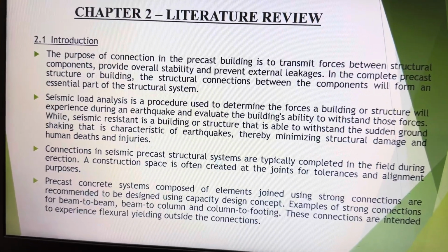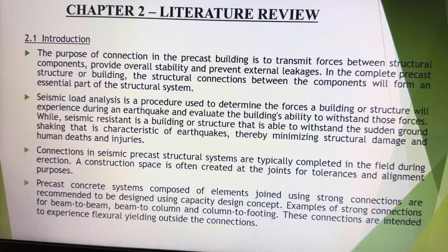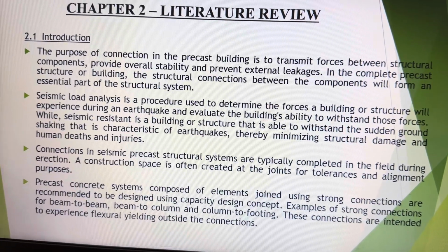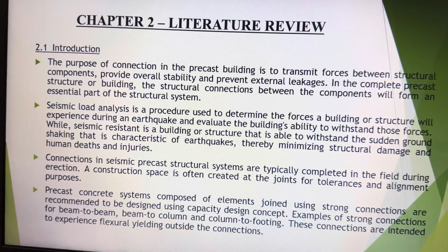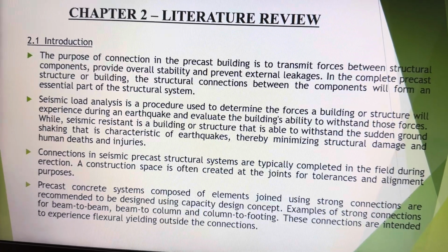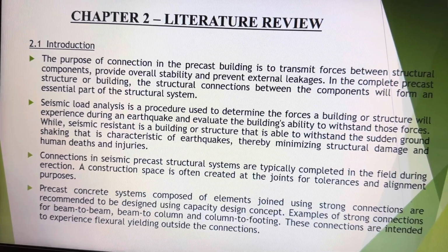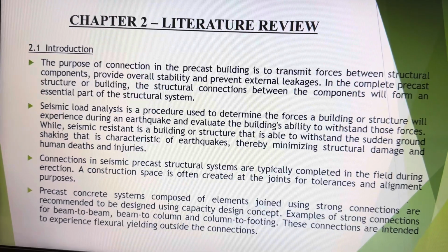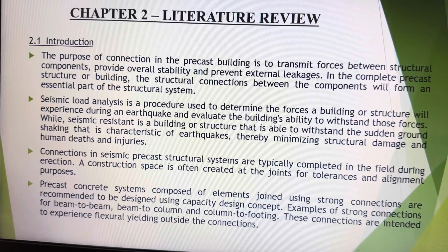For literature review, as introduction, the purpose of connection in the precast building is to transmit force between structural components, provide overall stability, and prevent external leakage in the complete precast structure or building. The structural connection between the components will form an essential part of the structural system. Seismic load analysis is a procedure used to determine the force a building or structure will experience during an earthquake and evaluate the building's ability to withstand those forces. While seismic resistant is a building or structure that is able to withstand the sudden ground shaking that is characteristic of earthquakes, thereby minimizing structural damage and human death and injury.